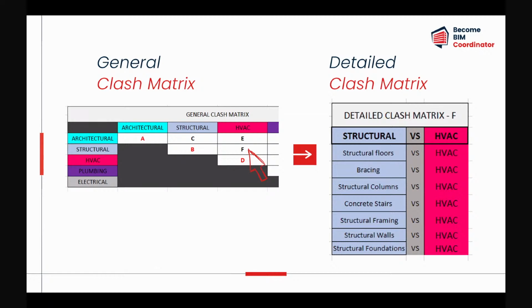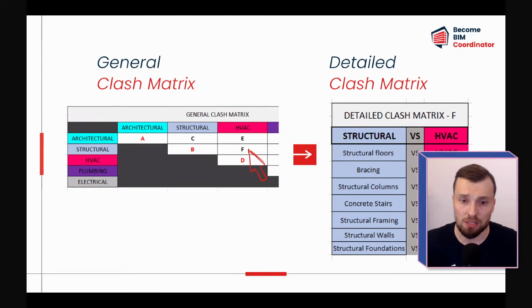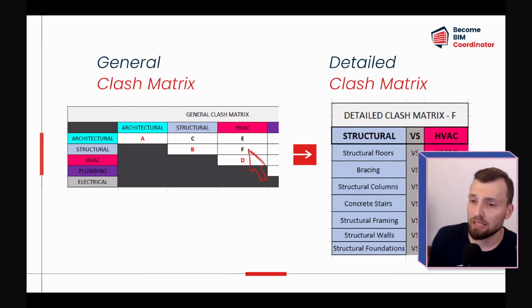And about the clash matrix, because I showed you a very general one, but on most of the projects we are going to dive a bit deeper. So we will need to create a more detailed clash matrix. Here you see, for example, that we break down the major systems into subcategories.